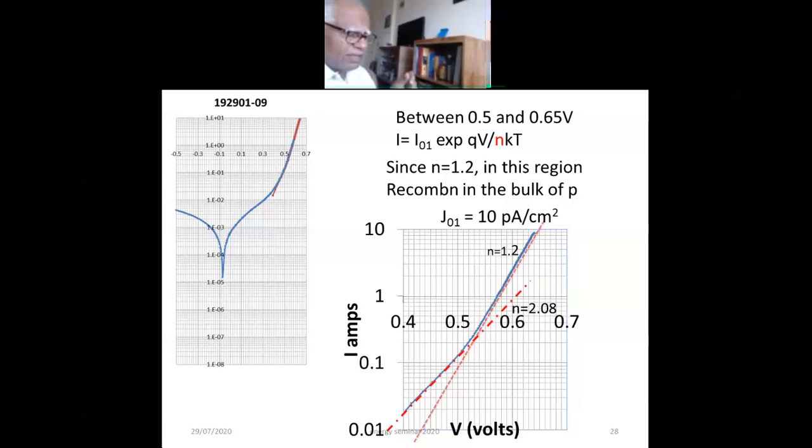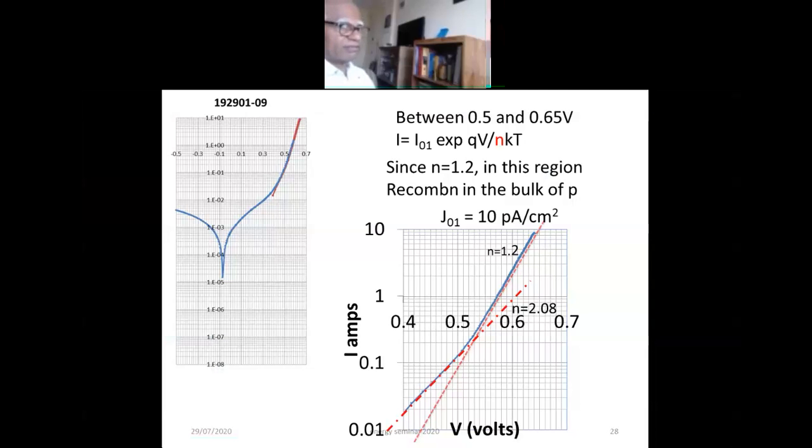You have to design it such that the current is the same through both the cells, but the voltages add up. So the cells which are 40% efficient, 45% efficient are made up of 3 or 4 cells with spectrum splitting band gaps. They have 4 different materials all grown one on top of each other, and the voltages add, and that's where you get a large amount of the efficiency gain. So you get to 43%, 44% in tandem cells.